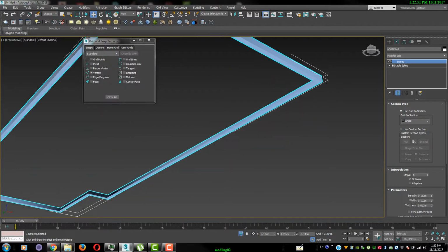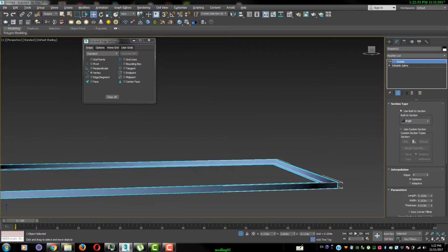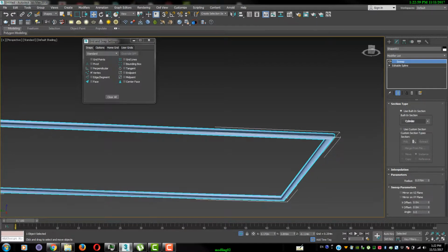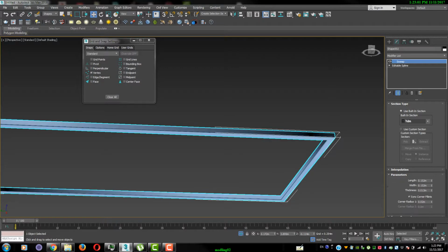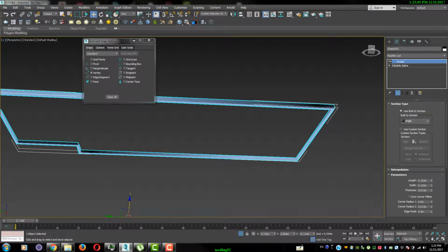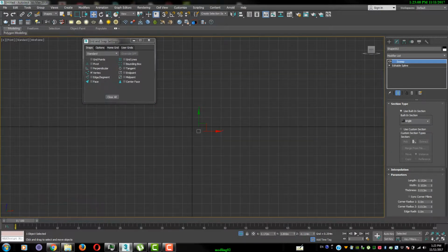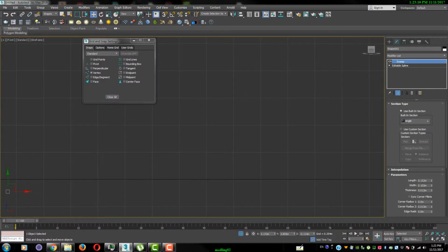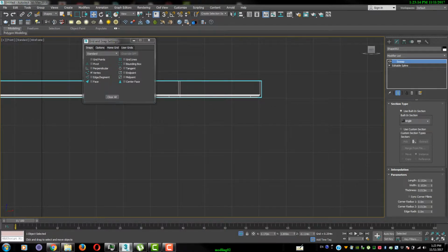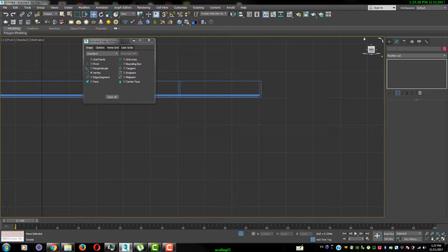So this swap, I choose my section: bar, channel, tube, anything. Also we can customize one for us. I press F because when you draw something 2D, you're drawing in the 2D view, not the 3D perspective view. So I want to start drawing my section.